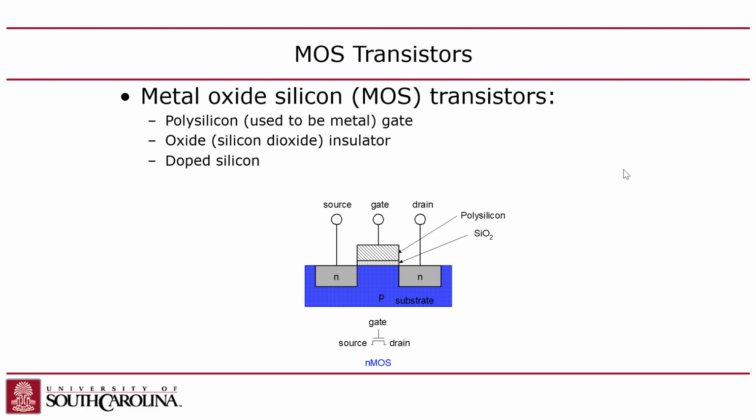They're pretty slow, right? So even once you put those minority carriers in the channel, you still have to make them move charge from one side to the other. And so the mobility is fixed. That's a physical property of the semiconductor. So the problem is, in addition to having to charge this bad boy up, the speed at which you can get things across depends on the mobility, how fast you can move. You can't change the mobility, but you can change how far they have to go.